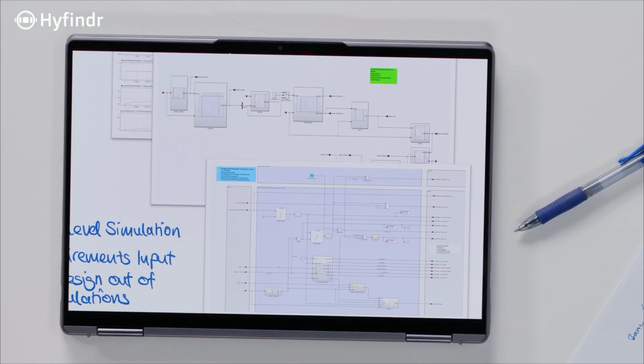When we're talking about a compressor, you will not find one that fits exactly the specification. So you go in contact with different compressor suppliers, and they normally send you the performance maps. We insert the performance maps into the simulation model, and in the end we get a very precise simulation model. It's called the iteration, and this is a kind of digital twin.